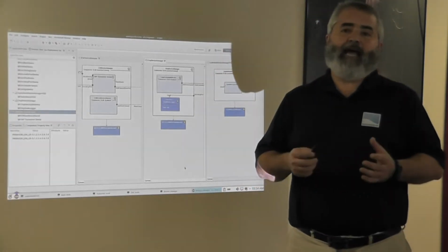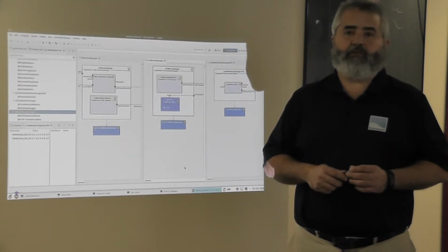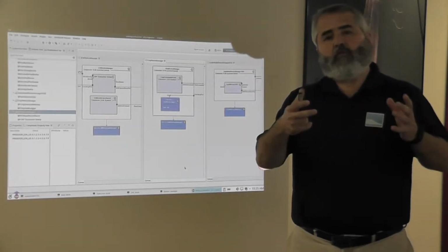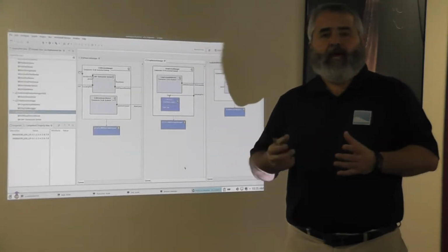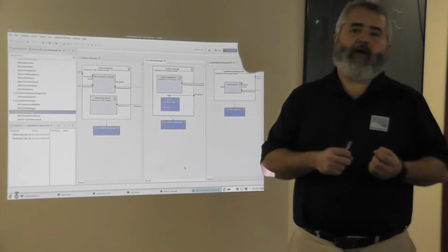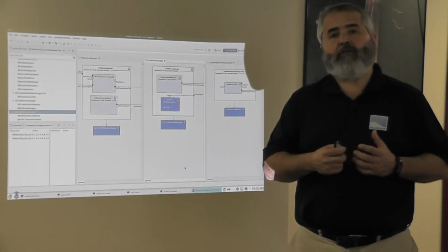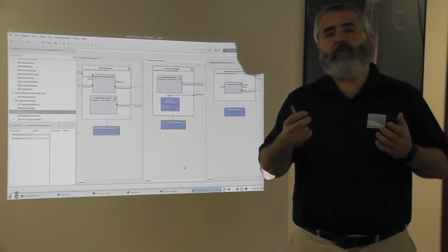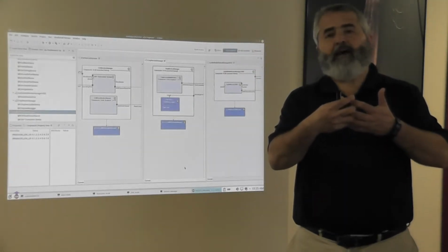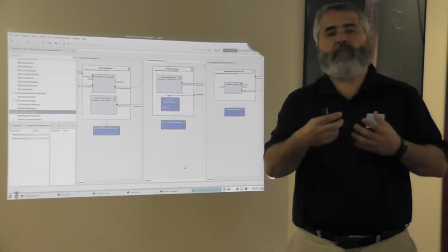But before we start with the actual demonstration, let me introduce a key feature of the SCA that enhances application portability. That feature relies on hardware abstraction for an SCA waveform to be able to be moved from one platform to the next. An SCA application is not permitted to use native drivers to interact with the physical hardware. And the reason should be obvious. It's because the moment that we use native drivers to interact with an application, that application becomes tied with the physical hardware, with the physical platform.